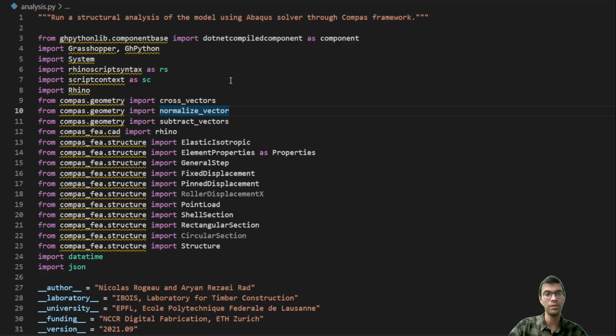These libraries are used to define the Grasshopper component that we've already developed inside Manis for structural analysis. We are importing the geometry and using vector calculations to identify the local and global coordinate systems of our structural components, shell elements, and specifically our linear elements.